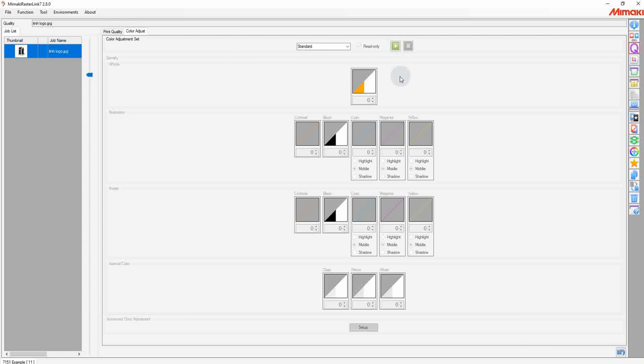This is where you can do adjustments to your color in Rasterlink. Simply type into the top box, click the plus button to add it, and now you unlock these options. Now, mind you, you're able to swap your density of ink colors here, whole, individual, on the curve, but there will be no visual preview until this is actually printed. Some people like to work this way, some don't. I recommend a lot of testing though if you want to get into using this.